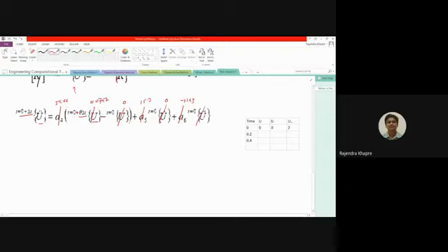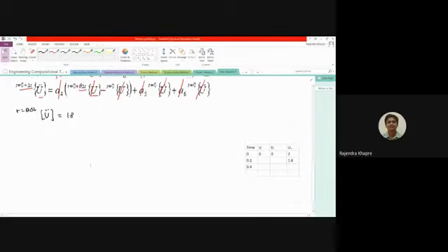So you can substitute these values over here, and if you solve this, all you are going to get is the acceleration at theta times delta t. This value is coming out to be something like 1.8. So here in this table now I can write this value is 1.8. Using this expression, first we get the value of the acceleration. Then once the value of acceleration is known, you can start working on the velocity.